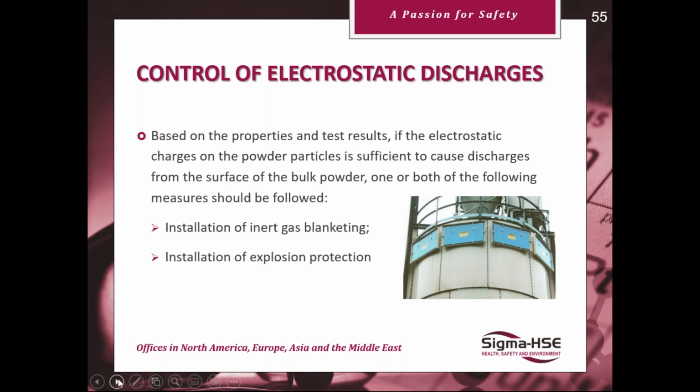Control here, based on the properties and test results, if the electrostatic charge on the powder particles is sufficient to cause discharges from the surface of the bulk powder, you may have to use inert gas blanketing, or if you don't mind having explosions going off, you could use explosion relief panels.